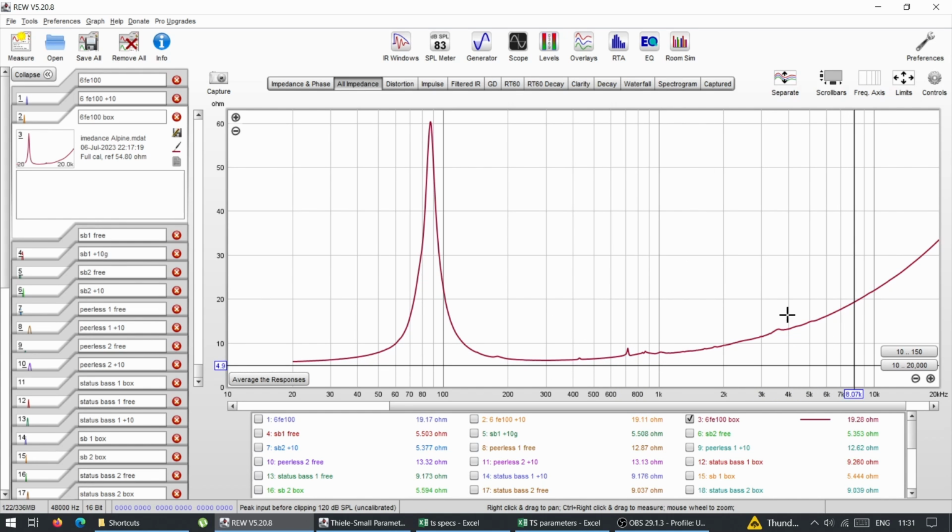This tool is amazing if you like building home speakers and you want to troubleshoot frequency response issues. If I applied some damping in the box, like some polyfill, these blips would go away. And these blips appear in subwoofer boxes as well.